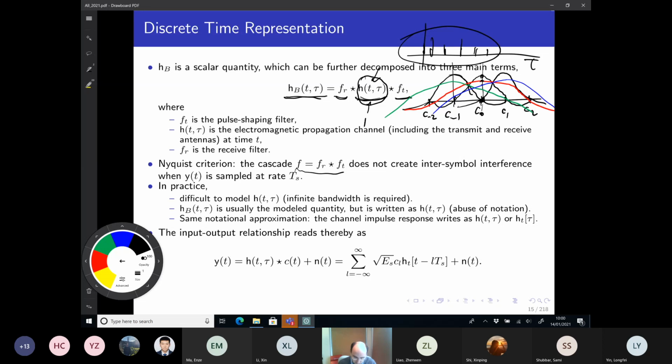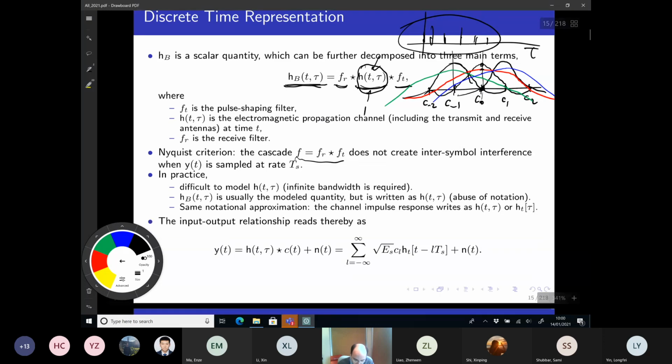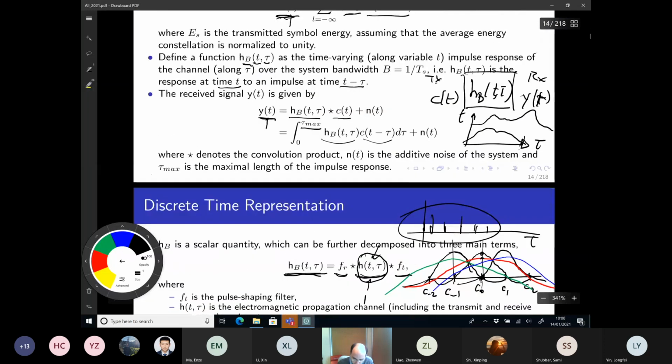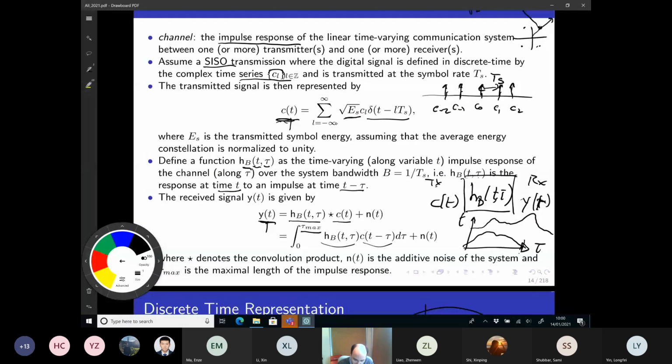So this is the interference between symbols. And that comes from the fact that now this H of f here does not satisfy the raised cosine filter criteria anymore, and then I have this interference between symbols. And so this is what you see here in this relationship. What I'm doing here is simply taking the C of t and plugging it into this relationship. So I'm doing the convolution, and because you have a train or a sequence of Dirac pulses, if you convolve this with any impulse response of the channel, essentially the impulse response of the channel will be replicated around each of those Dirac pulses, right?